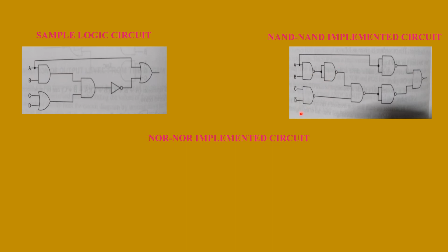These 4 I could implement with a single IC, because remember your IC 7400 encapsulates 4 gates, and similarly the remaining 3 could be encapsulated in your other IC. So to implement this, I need only 2 ICs, whereas using basic gates now I need 3 ICs. Similarly, even if I'm trying with fully NOR now, then I'll have the same.